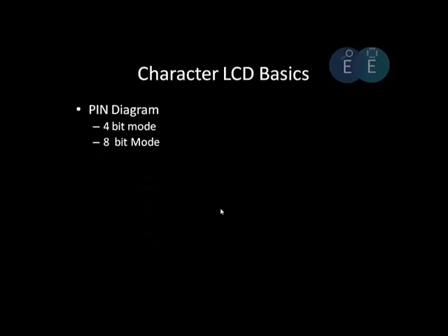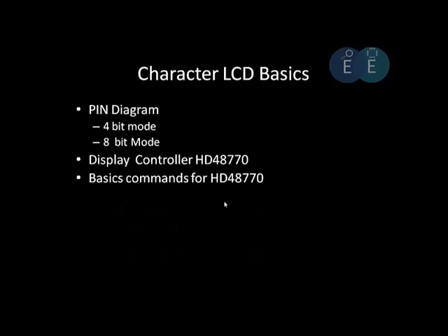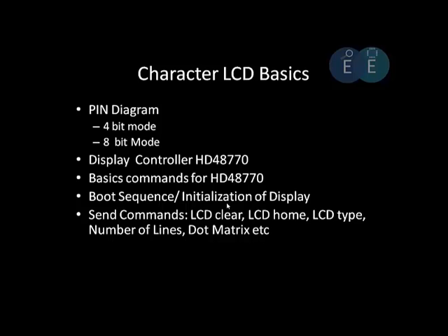So in the basics, we'll discuss the pin diagram of LCDs, the 4-bit mode, the 8-bit mode, and we'll discuss in brief the display controller. Then we'll see what the basic commands are, and after that we'll see the boot sequence or initializing of the display, and then we'll send some commands that are required to clear the LCD, then set the LCD at home position, number of lines, and the matrix, etc. And we'll also send data, as in we'll send some strings, and we'll see.